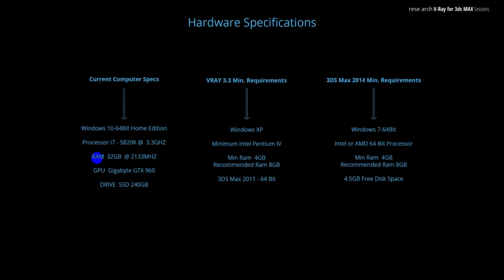than enough. But if you want to have Photoshop open on the side or maybe a second smaller scene in 3ds Max, 32 is starting to be actually quite little. So from the moment you want to use your machine for more than one scene or more than one process being handled at the same time, let's say rendering and post-production at the same time, you really should consider going to 64 gigabytes of RAM, because that's really going to help much actually.